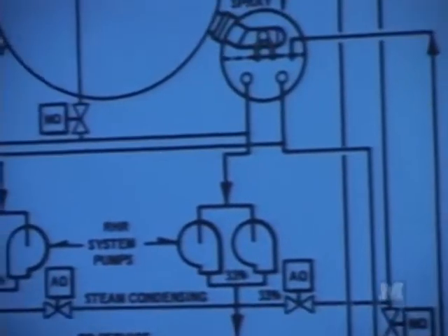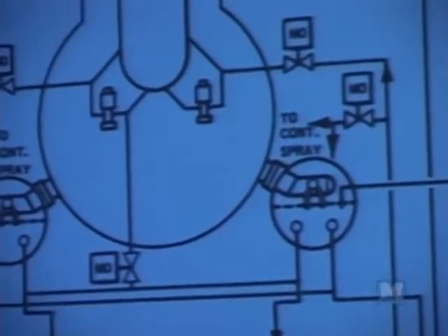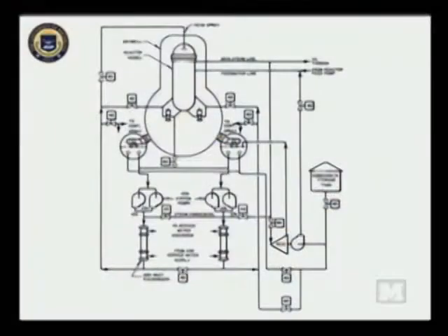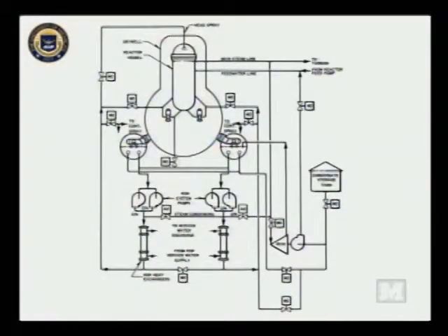And the steam would be produced and then would come out into the separation pool. And that was the heat transfer path. And there was another heat transfer loop that would take away heat from the separation pool itself that I mentioned. It's called the isolation condenser.